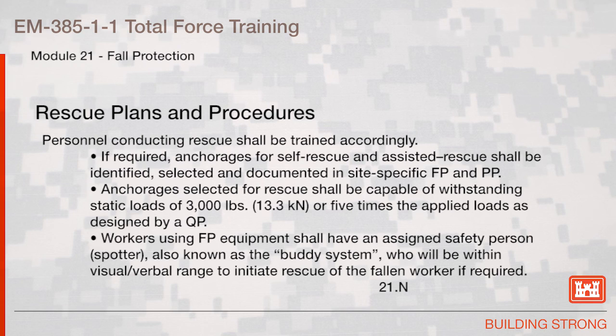If required, anchorages for self-rescue and assisted rescue shall be identified, selected, and documented in the site-specific fall protection and prevention plan. Anchorages selected for rescue shall be capable of withstanding static loads of 3,000 pounds or 5 times the applied loads as designed by a qualified person.